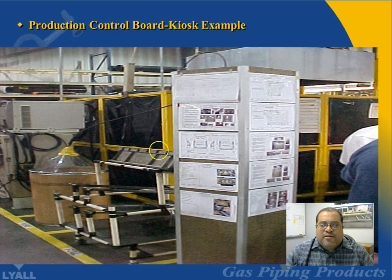Okay. And then, of course, you have your reference boards. You have your reference kiosks. People could walk over. If there's a frequently asked question, they could refer to these graphical work instructions, limit standards, especially when your standards are aesthetic and not dimension-based. Where you could easily use a print, you use your prints with tolerances and measuring equipment. If it's something visual, you need a control sample to go off of.